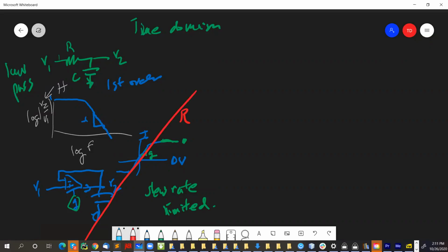So it's only good for small voltage changes. It can be a big voltage all the way from ground, over the whole operating range of this amplifier, but the voltage difference has to remain small enough to be linear. So V1 and V2 have to remain close to each other. You can't expect it to act linear for big steps in V1 or V2. V1 especially.